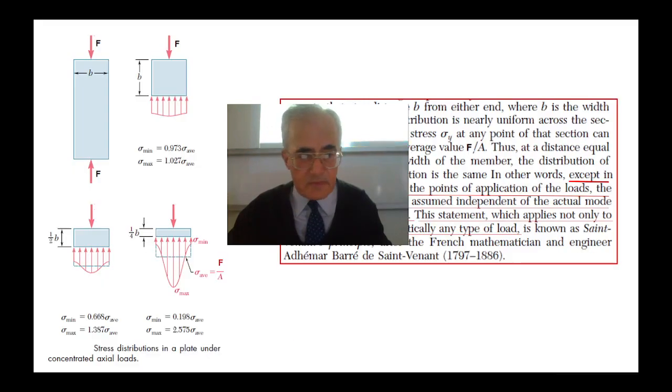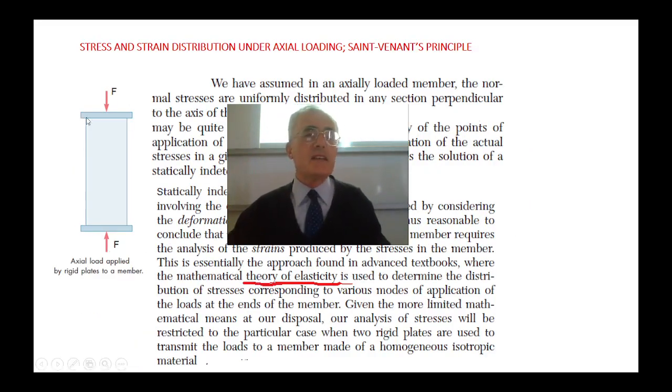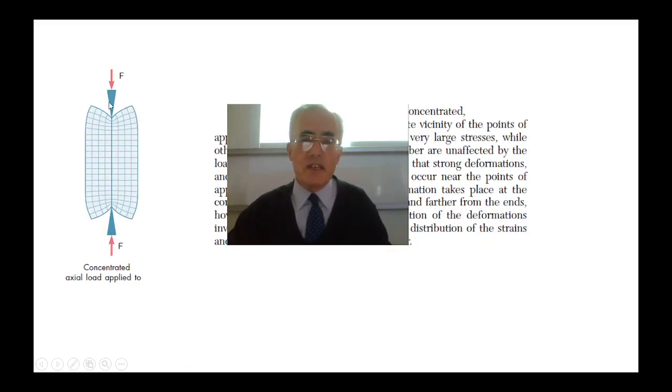If the contact area is over the entire surface, because you are using a special tool applying the force uniformly distributed, then that is okay. There will be no stress concentration. But if it is a point force, then in the vicinity of the point of application you are going to have greater deformation and also a greater stress value. This point of application is actually where the stress is going to be maximum.